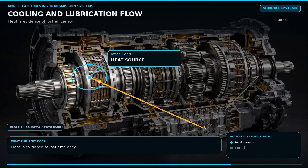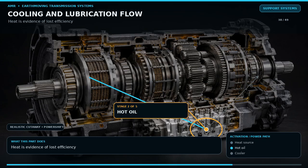Every transmission converts some power into heat. Converter slip, clutch modulation, hydrostatic leakage, bearing friction, and gear churning all warm the oil. Pump flow carries oil through the cooler and then to lubrication galleries. Orifices and drilled passages feed bearings and clutch packs. A thermostat or bypass may route oil around a cold or restricted cooler.